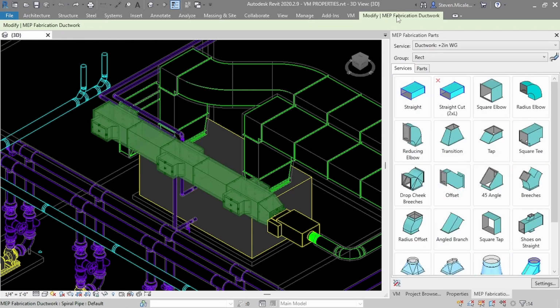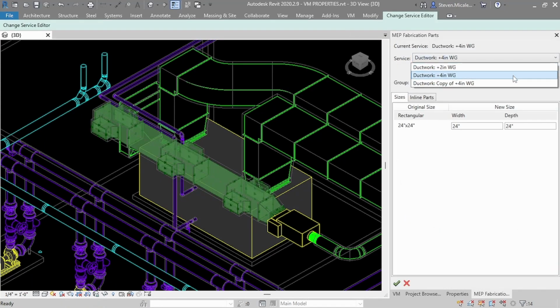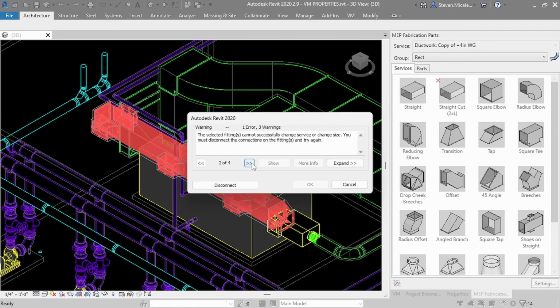The only Revit-supported method for geometry modifying service level changes is to use the Change Service tool via the Modify tab. This will force a redraw and replace of the selected parts using the default items and dimensions of the specified service. As you can see, this can have wildly undesirable results, wiping out any data, custom dimensions, tags and numbers that existed on the original parts.